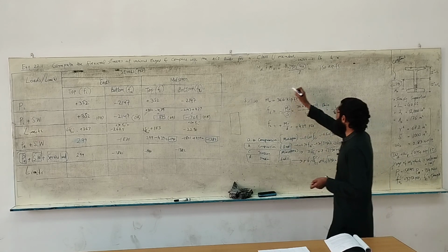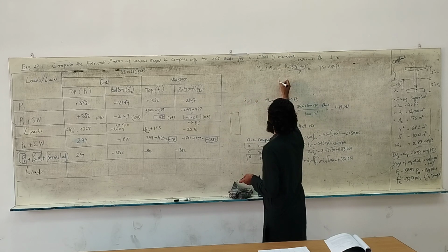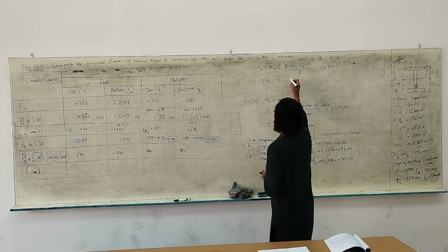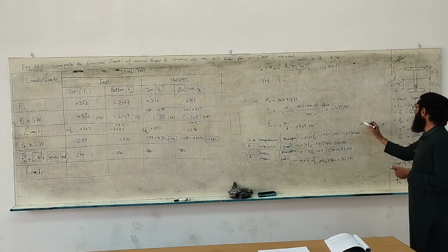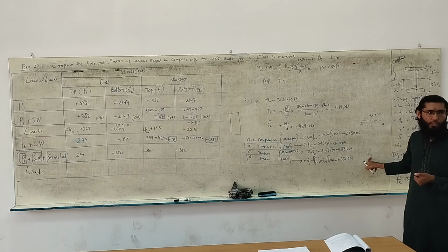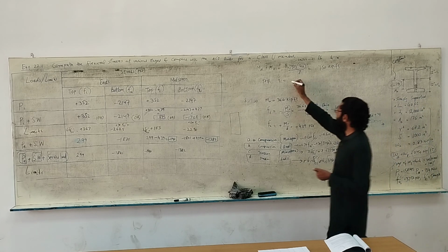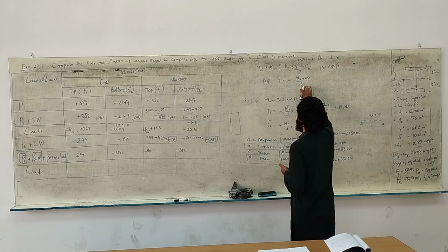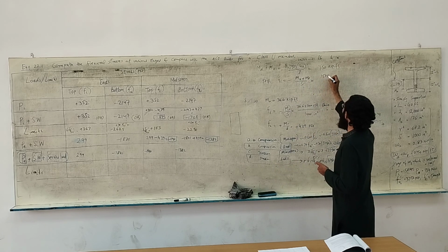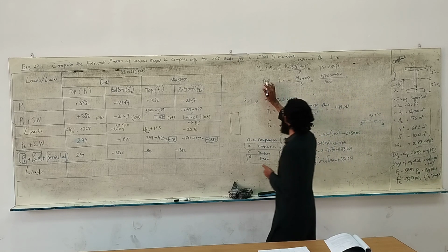Yes, 150. And what about the stresses due to them? At the top, again, if you have a simply supported beam with any UDL on it, it will produce tensile stresses at the bottom and compression at the top. So this will be minus (Md plus Ml) over S. Okay, so 150 into 1000 into 12 divided by 1000. We should get the answer for this.